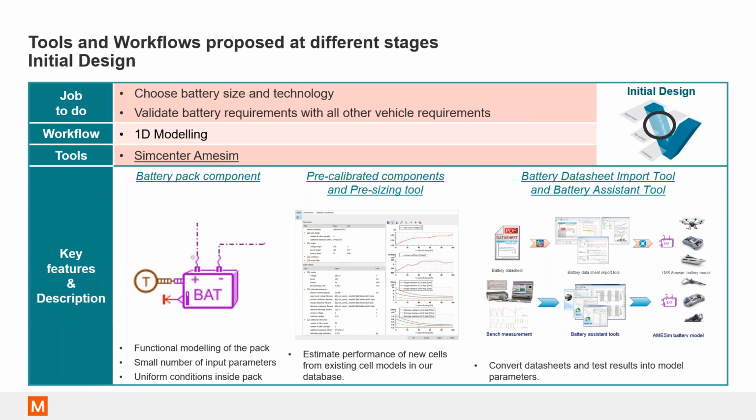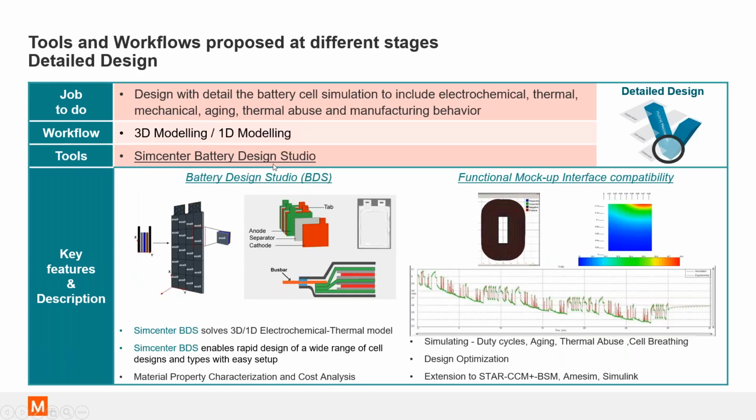So to create a more detailed model, what we can then do is collaborate with SimCenter AimSim and Battery Design Studio, where Battery Design Studio is a solution for doing physics-based simulation. So that would be for the electrochemical modeling, as well as, if I had, say, test results where I don't know anything about the cell, but I only have the test results, I could still create a cell based on my pulse data to create an RCR model.